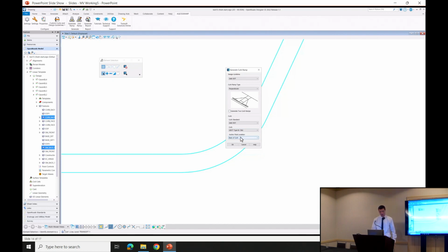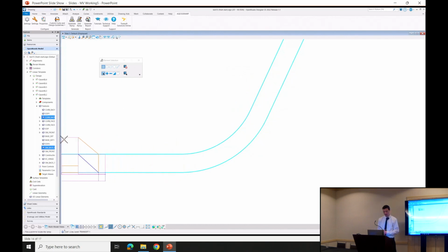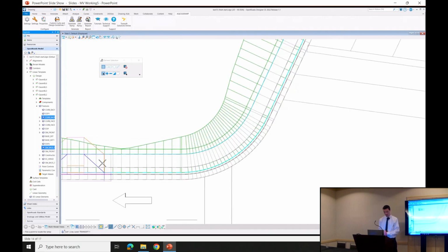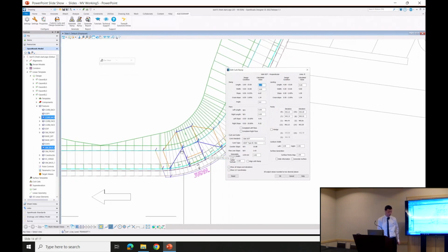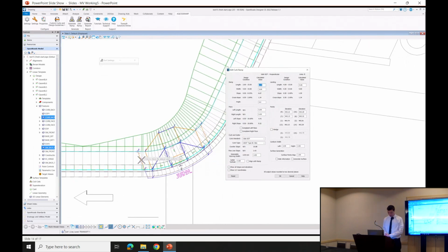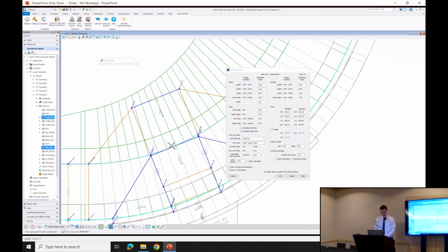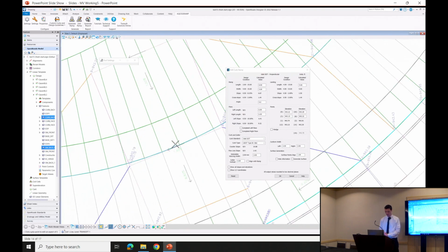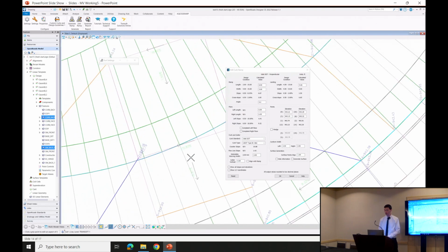When you have these elements, the specialized tool that I am using through this CAD platform, Open Designer actually, will give instant feedback. We can see the program reacts to the conditions of these elements and generates a curb ramp slope with the lines changing accordingly. Here's a preview that's being shown. And I have the freedom to make fine-tuned adjustments to ensure comfort for people navigating the curb ramp using mobility devices such as manual wheelchairs, while also minimizing the footprint of accessibility for this infrastructure.